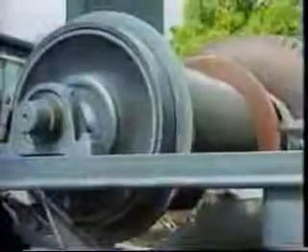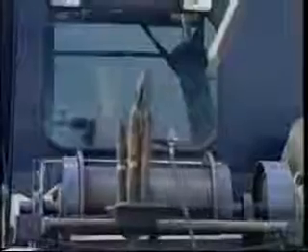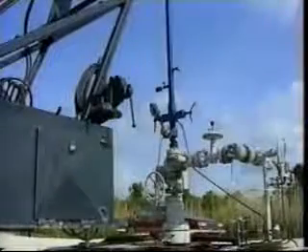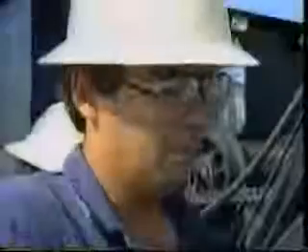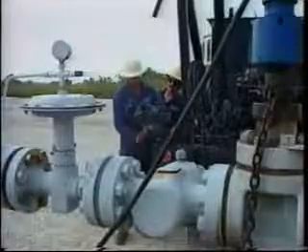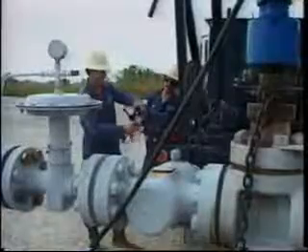This is a slickline operation. Over the course of a morning, the crew will make 6 trips in and out of the well to replace 3 gas lift valves with 3 dummy valves. This procedure is required in order to prepare gas lift wells, such as this one, for stimulation with acid.